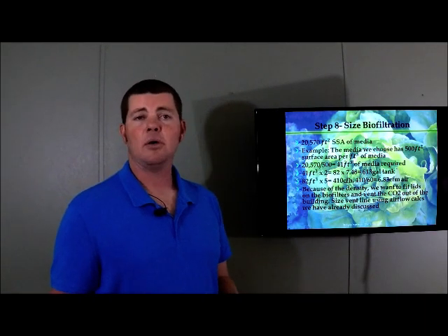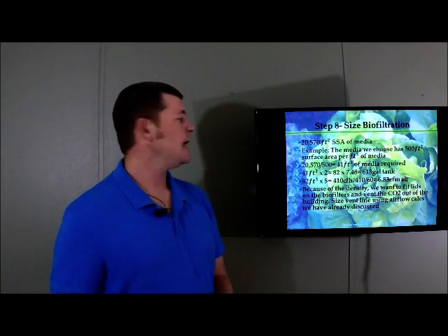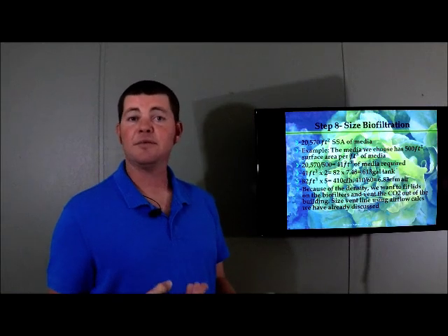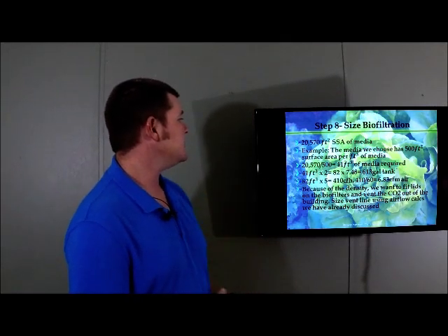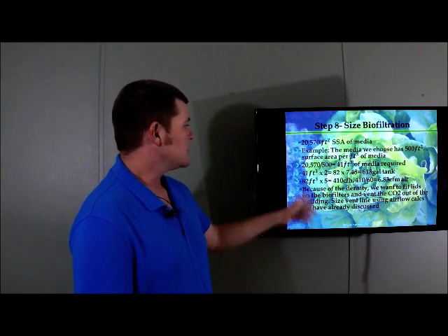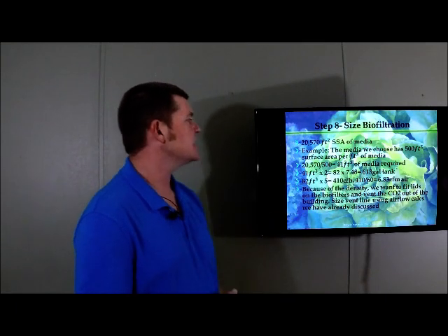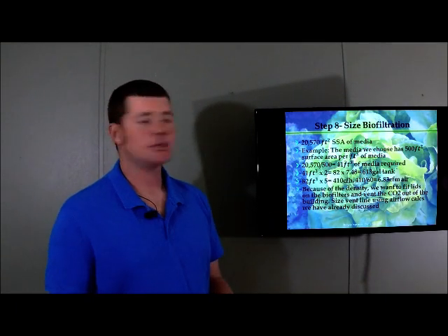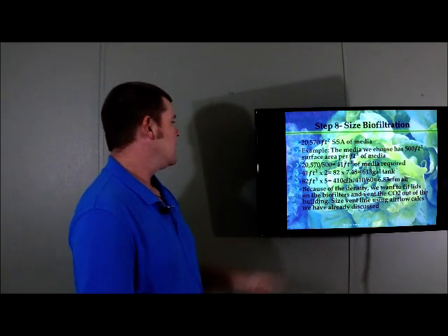All we need to know is what's the SSA per cubic foot of media. And any biomedia out there will give you that information. That's how you size it. 41 cubic feet times 2 equals 82. We're sizing the tank here, okay? 82 times 7.48 gives us a 613 gallon tank to hold this media. This would take up half of that tank.